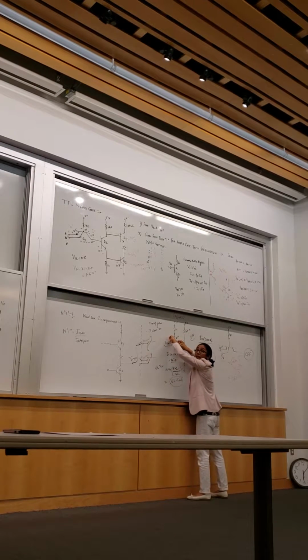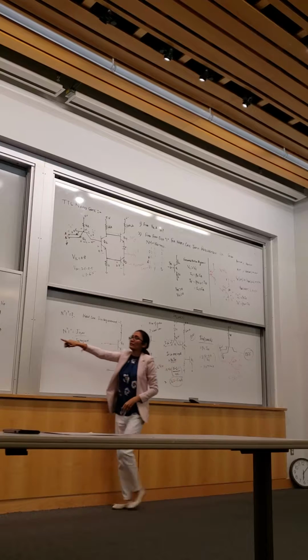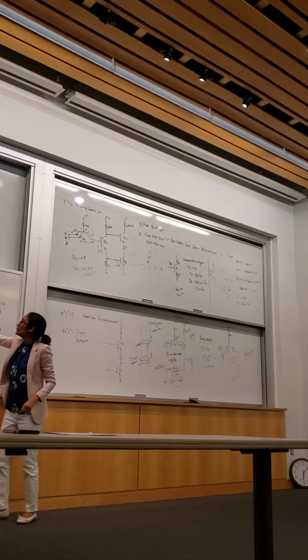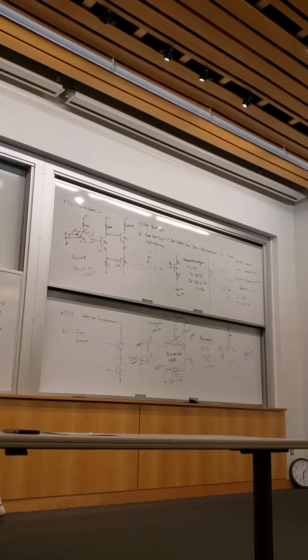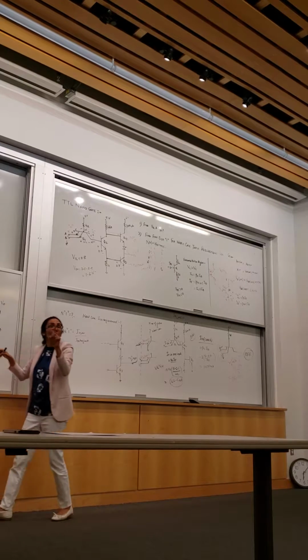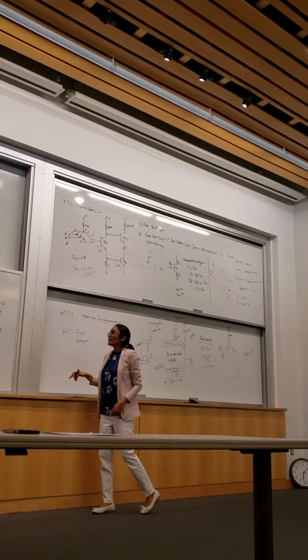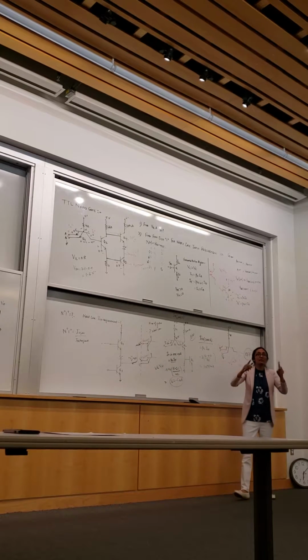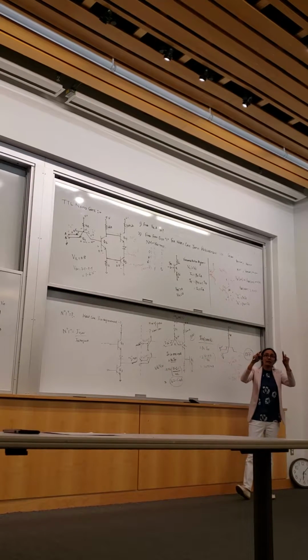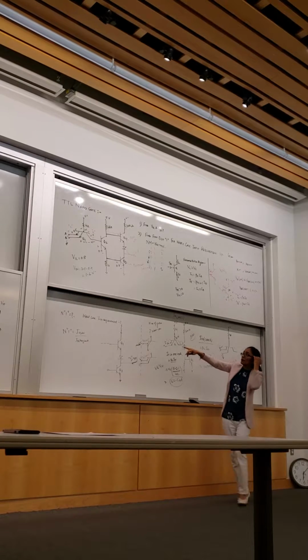Think of this as two diodes, as I have shown here. So this base is sitting at 0.7 volts. So the base current is (5 minus 0.7) divided by 4K. It's splitting into two branches, but we are interested in looking at only one branch. Okay? So these are the two cases when you are asked to find noise margin for logic low. We are right now doing it for logic 1.